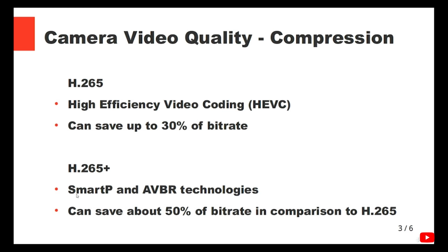For instance, if you are using 8 megapixel cameras, I'm sure you would have to use H.265 plus. Obviously, as I mentioned before on a couple of occasions, when you're picking that type of camera, you have to make sure that your NVR can handle that, unless you want to downgrade inside the camera, so in the camera settings change to a smaller resolution.